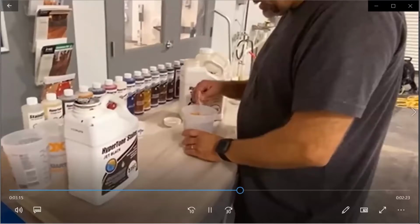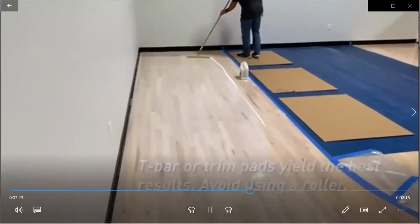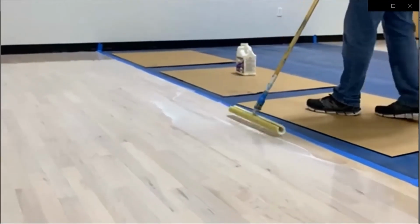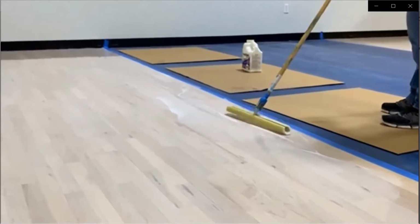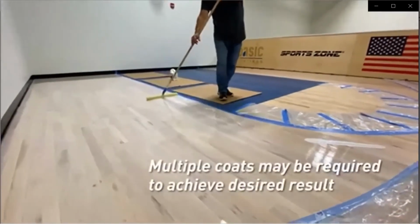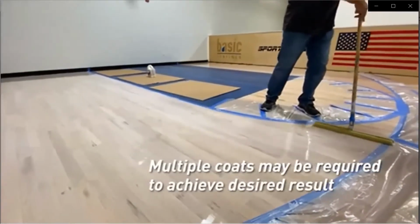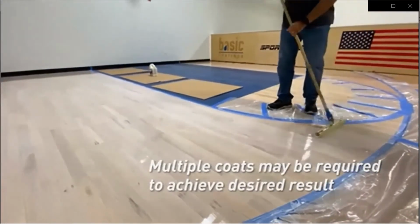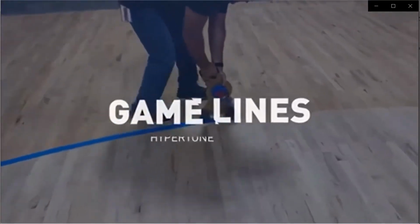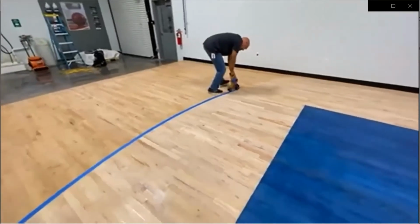Using a T-bar or trim pads will yield the best results. Avoid using a roller. Use care to apply the tinted finish in a uniform thickness. The initial coat of tinted finish can appear streaky. As you apply subsequent coats, the tinted finish should appear more uniform in color. 2 to 3 coats may be required to achieve the desired look. HyperTone stains are versatile enough to be used in place of paint for your sport flooring needs, including game lines.